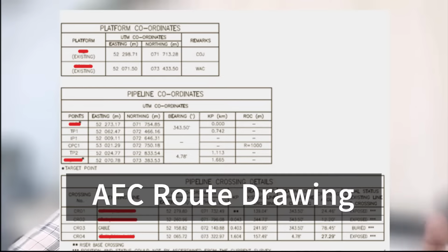First things first, as a surveyor you must have the approved-for-construction pipeline details and a bathymetric chart showing everything that is underwater, all the sonar contacts, depth of the pipelay route and any other significant information.